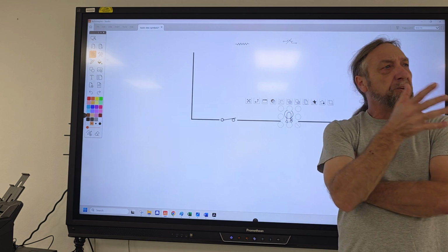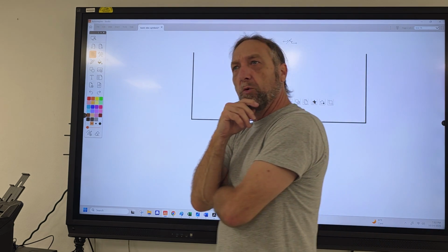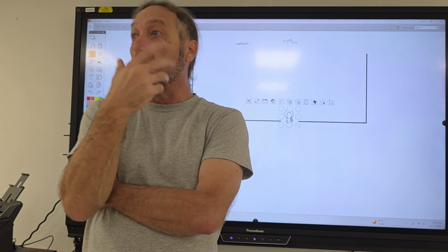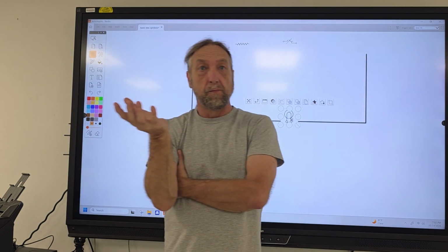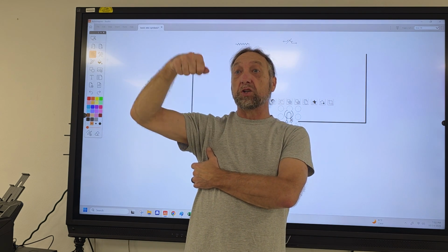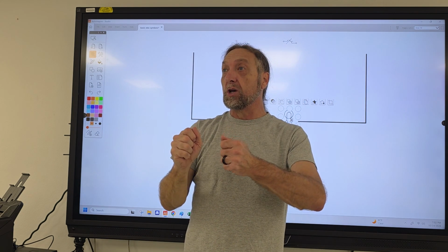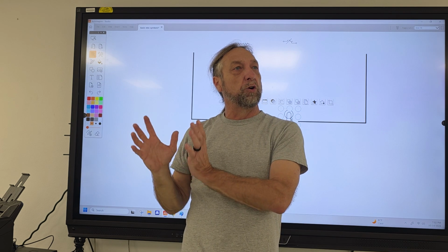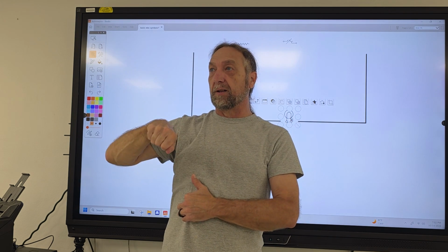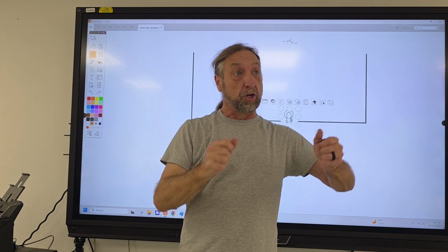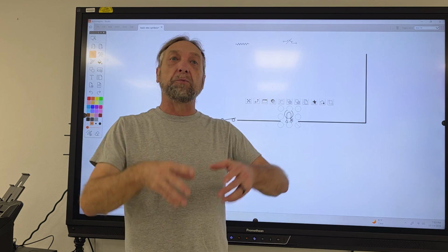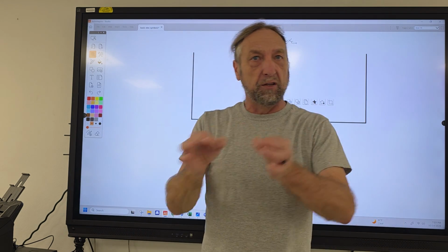But what else in the machine could stop the drain pump from working? A switch. A leveler, a clock, a control board? Yes. What about a lid switch? If the lid switch is broke, it may still wash. On some machines the lid switch is only good for drain and spin, because we don't want it to spin while the customer looks at that lid. So some machines will wash but will not spin. So now it comes down to machine specific.